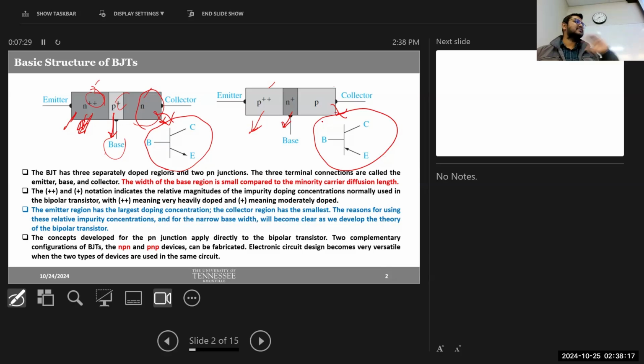When you take the circuits course, like the 336 electronic circuits course, where you will learn about BJT-based circuits, or also Dr. Rajesh might teach you some BJT-based circuits in the next lectures, there you will see these symbols. You will not see these structures anymore. You will only see these two symbols for NPN and PNP BJT. And you can see they are pretty similar. There is only one difference, which is the direction of this arrow.